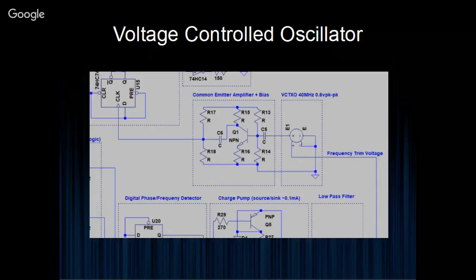Different oscillator classes have different pullabilities. This particular one is designed to be a sort of instrument reference, and as such, I think the pullability is 116 parts per million per volt. So over 10 megahertz, that's what, 7 kilohertz or something, is that right?